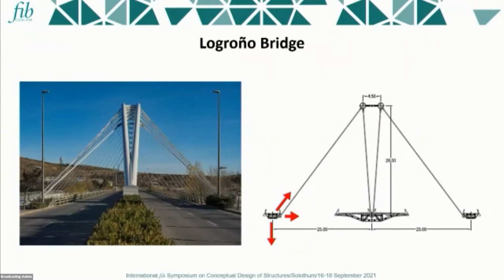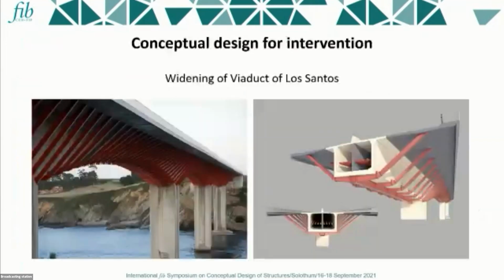The lateral force by the cable is not only for hanging the pedestrian parts, but also for stabilizing the very shallow arch. The force compensates the horizontal arch thrust. So I love this bridge, and I understand. I have never been there, but I just see the photos of the structure.